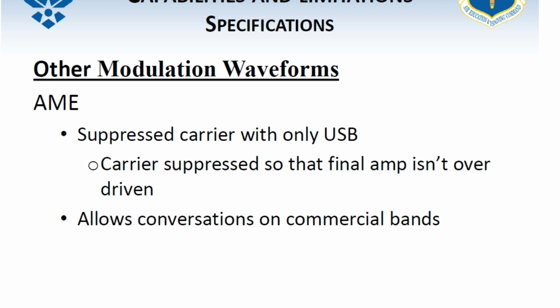Okay, thank you. What you're talking about is kind of like if they programmed a radio for receive only, which is an option you can do with that program I was showing y'all. With the radio, you can set it up so that it's only in receive, and you can't transmit back as much as you want to. Even if you had a handset on there, it won't let you if that's programmed in. All you can do is listen. I think that's more of what you're talking about.